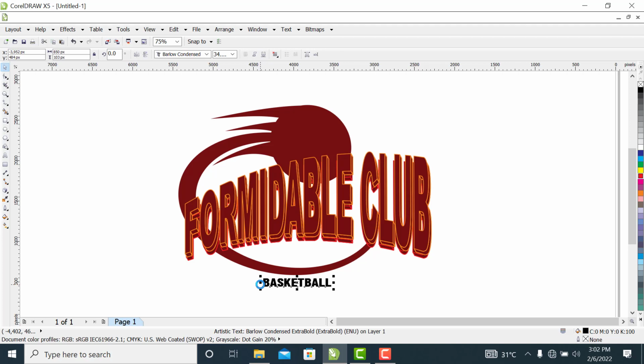So what I'll be doing next is this. I'll work on the text. I'll turn it upside down. So how do I do that? I'll just come to this part where I have mirror horizontally. I'll click on it. Can you see? The text is upside down now. So I need to fix this text to a part. The reason why I'm doing this is because I'll be fixing it to a part and I'll be turning the other way so that it will fit in perfectly.